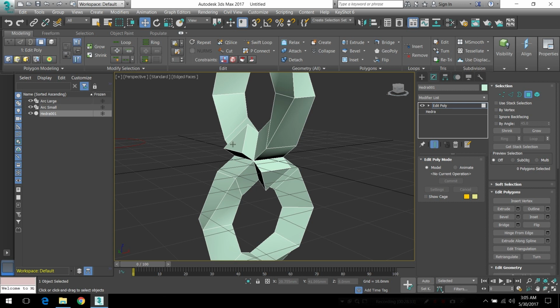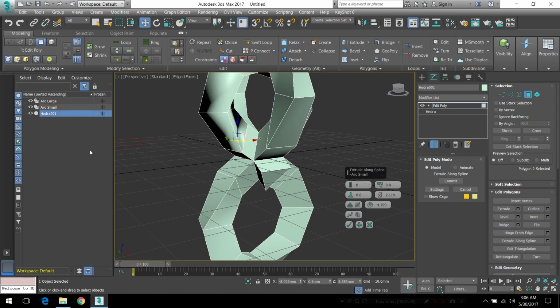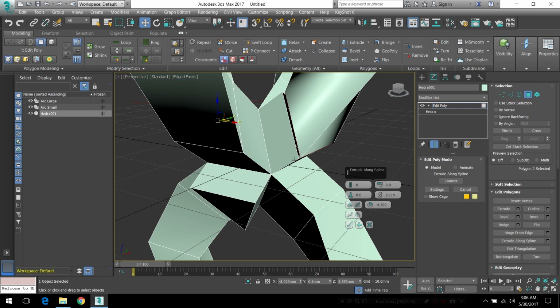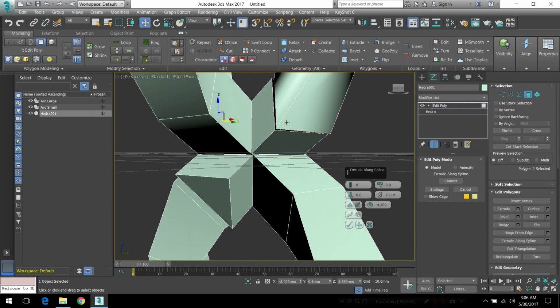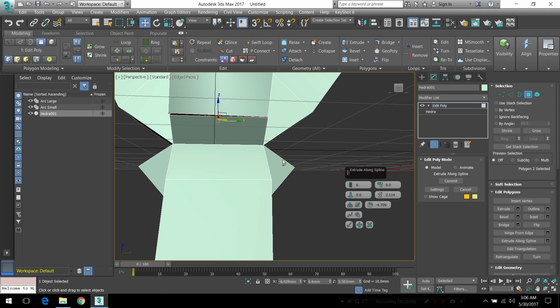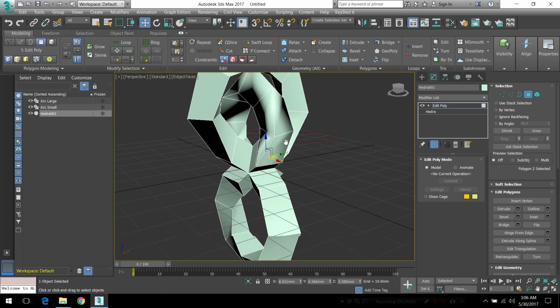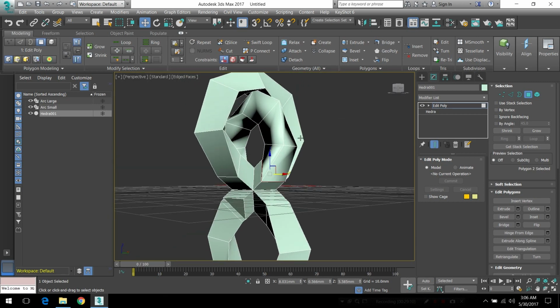And it's the same procedure. All right, except now, when we bring up Extrude On Spline and we go to pick our spline, obviously, we're going to pick the arc small instead of the larger one. Okay? And you can see that the previous rotation value was actually still valid for this extrusion. It's lined it up very nicely here. I don't even have to really make any changes to any parameter. I could just go ahead and accept that. So that doesn't happen all the time, but here it's happened and I'll take it.